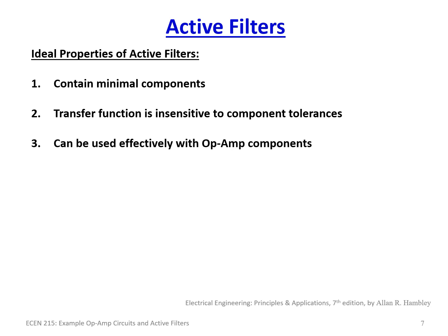You want to make sure that it is effectively using op amps, because op amps, as we've learned, are a very powerful integrated circuit. They allow us to isolate different filters in different stages. So they're really great. They have an infinite input impedance and near zero output impedance, ideally, so they're great. But at the same time, there are some limitations. There's limitations on the gain. There's limitations on what we know as the gain bandwidth product, what is the frequency range. So the nice thing about active filters is you want to make sure that ideally you use the op amp correctly.